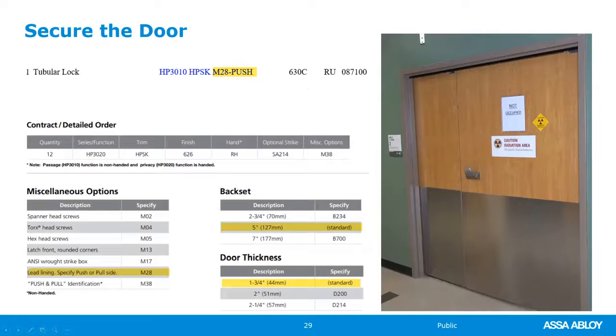If it's a regular mortise lock or a mortise lock with a rose or a cylindrical lock with a rose, you can lead wrap the rose or you can lead wrap the case. But the lock set is pretty much, you should specify lead lining for any kind of lock set because you're removing material from the meat of the door.